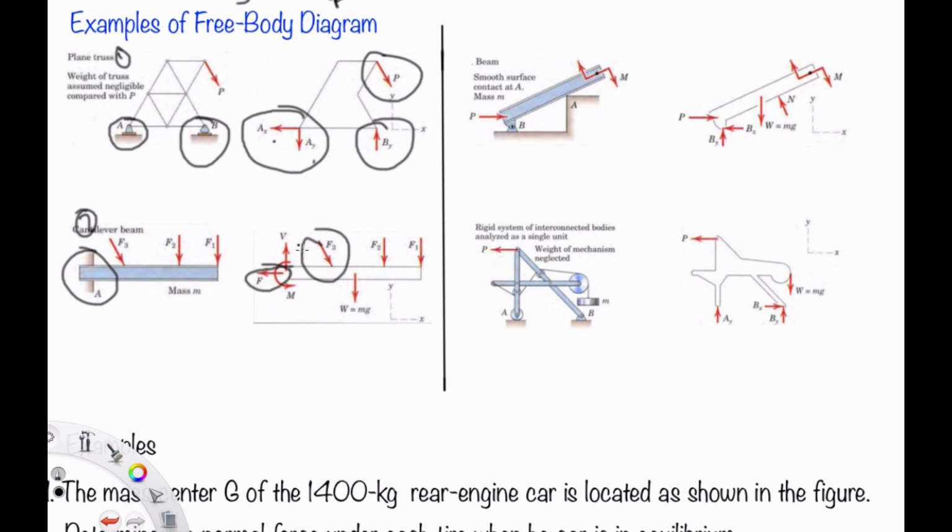It is the opposite of this one, and the shear also has to be vertical, because we have the applied forces and the weight, all of them toward the bottom, so the reaction has to be up, and all of that tends to rotate clockwise. So the moment here has to prevent the rotation, so it has to be counterclockwise. That's what I mean, that this one is clockwise, and the moment has to be counterclockwise to prevent the rotation.